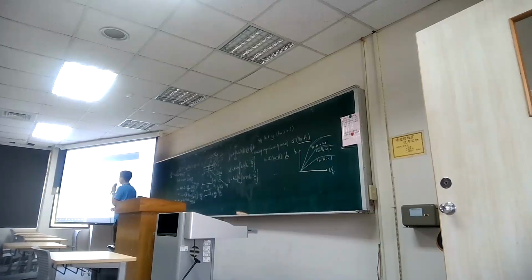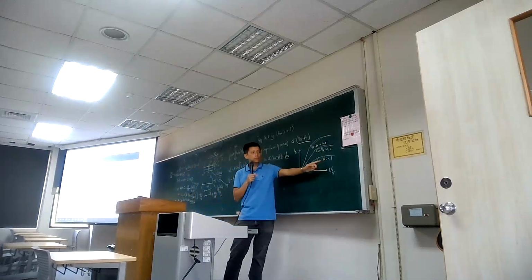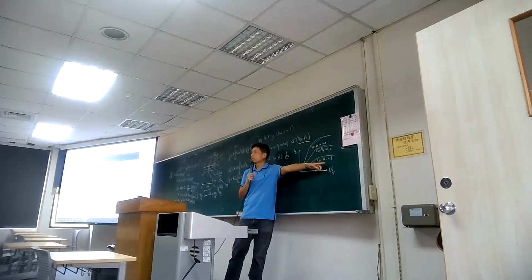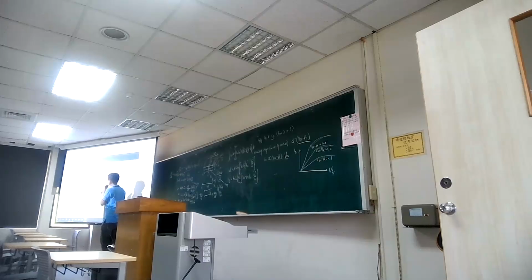Exactly the same. But in the saturation region, what is happening is that the drain-source voltage is much higher than VGS minus VT. For instance, VGS minus VT is only 0.1 or 0.2 volt, but VDS is maybe 3 volt. So if you get a large contribution on the second part, you can replace the VDS here. Since VDS is much larger, you can just place VGS minus VT into the VDS term. You pinch off the channel, and how much channel is available is limited by VGS minus VT.